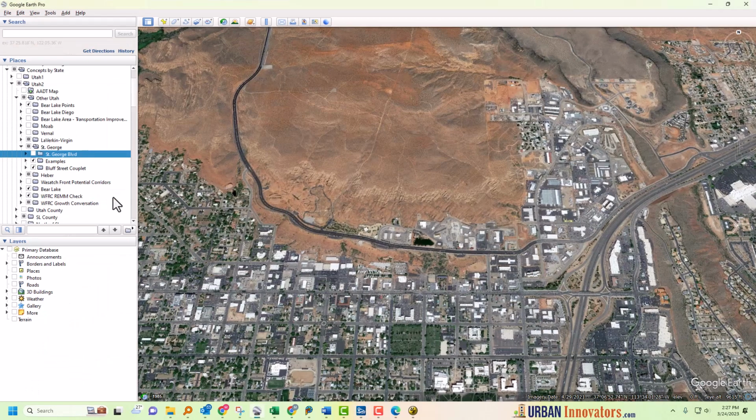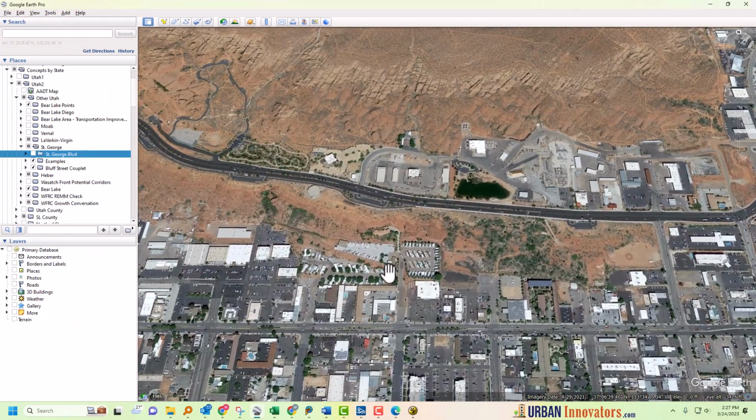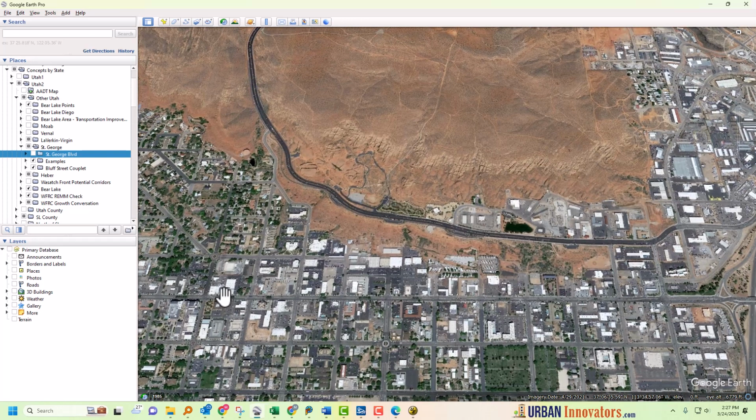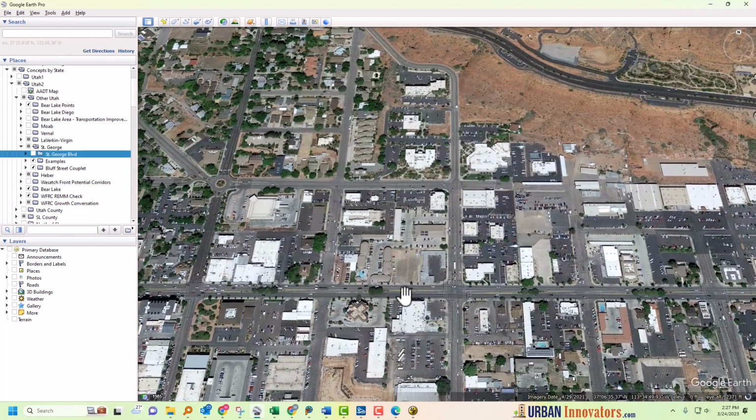This is a problem in the data and the way that the model is set up. This is those two roads. So St. George Boulevard is this one, and it's defined as 33 because it's a principal arterial. This one over here is also 33 because it's also a principal arterial. Now I ask you, which one of these is going to be faster? And considering free flow speed is supposed to take into account traffic signals and cross streets, this one's going to have a ton of traffic signals all along it.